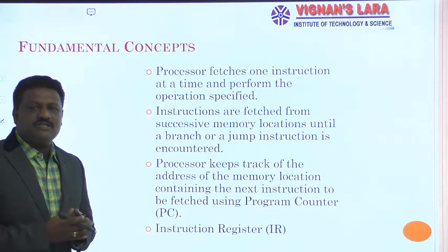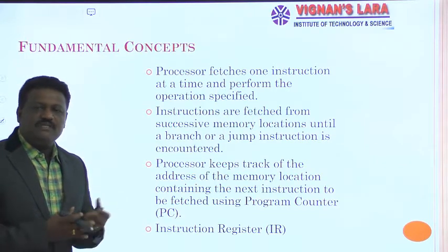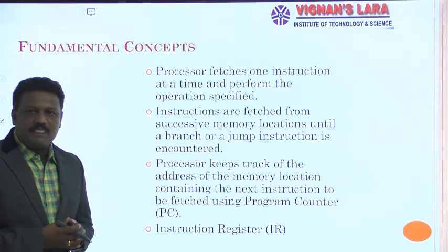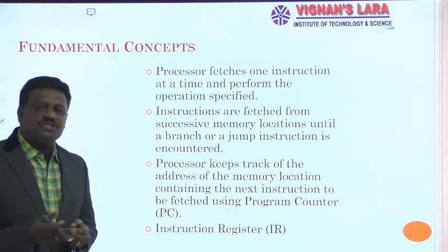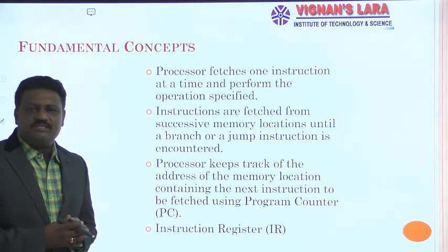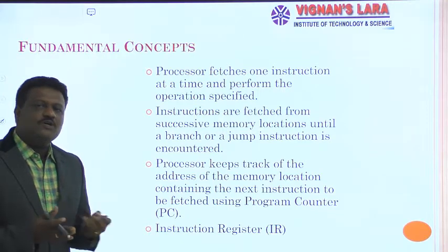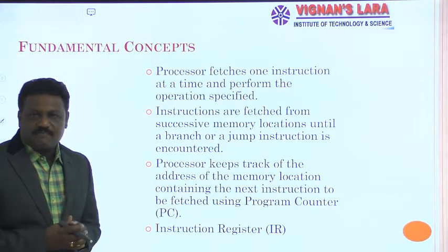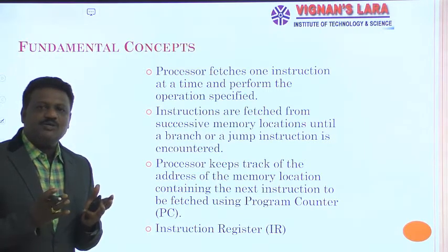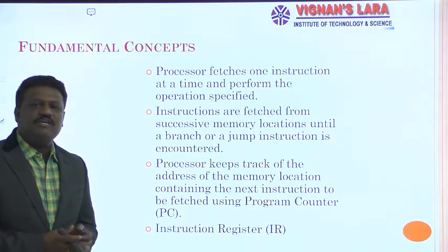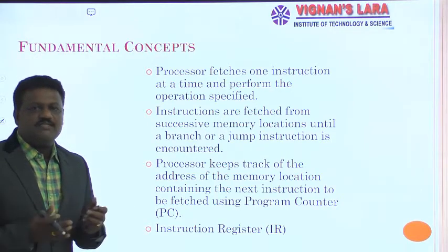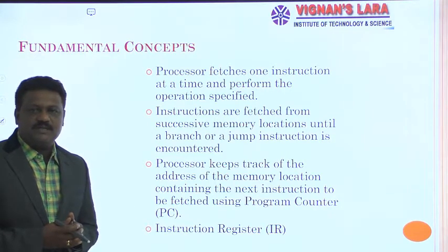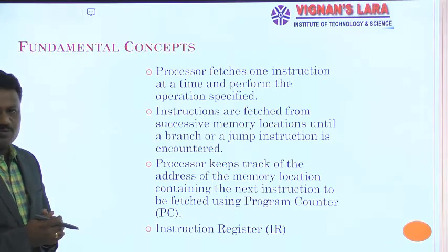Once we fetch an instruction, we receive that instruction from the memory. Before execution of it, we decode the instruction. In the decoding process, we identify what the operation and what the operands are. And according to the operation, we perform a particular task in the execution of an instruction. So that is the meaning of the first one.